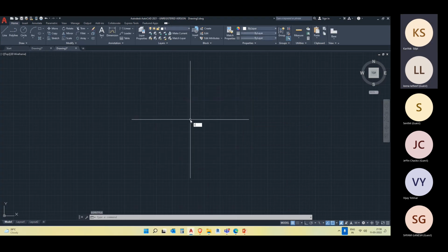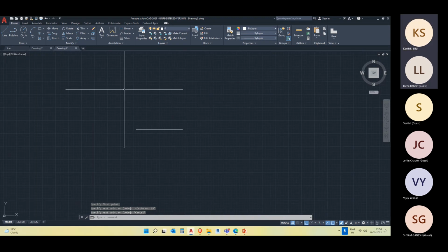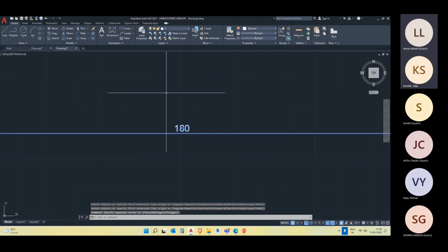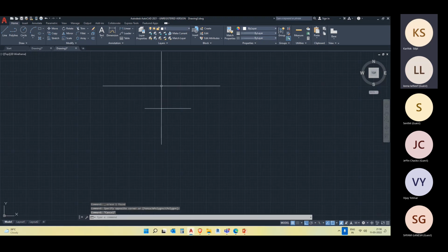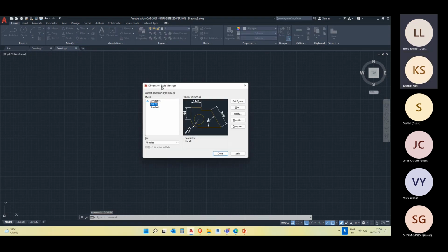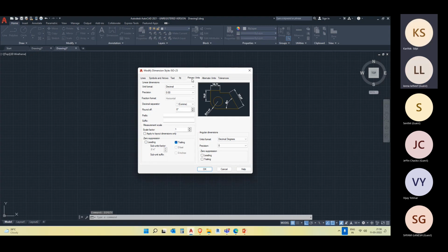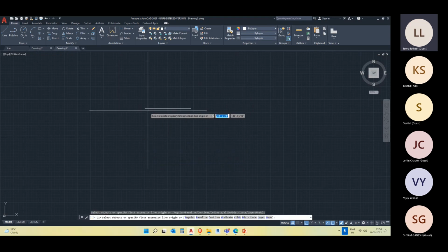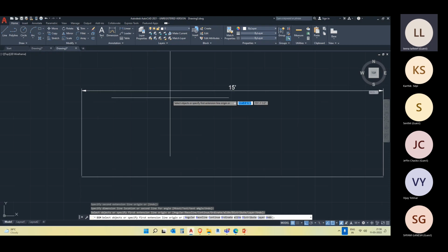So now let's say I have a line, of say 10, 15 feet. If I measure the dimension over here, see, it's still not functioning. It's functioning, but it's showing in inches. If you want it in feet, you have to change it to feet, like in the dimension style. Just go to modify, primary units. You can see it's still in architectural. Now, if I go and change, it will be displayed in feet. You can see it has changed now.